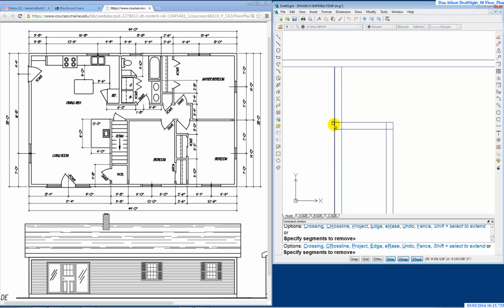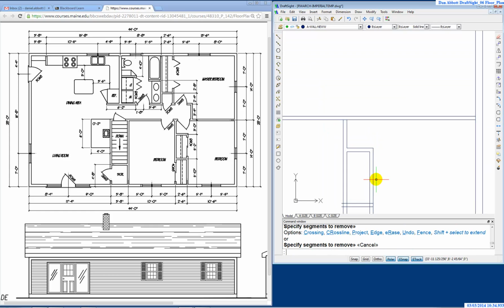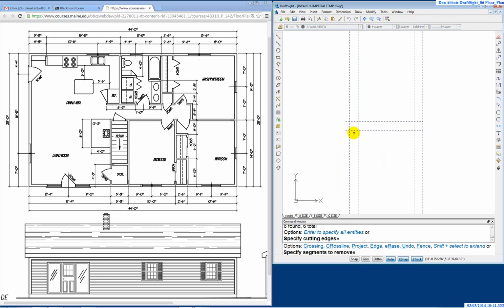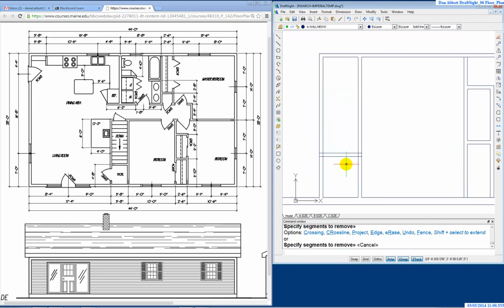Now I use a trim command, and I'll clean up this wall segment by picking each of these little pieces, including this one. And this one. Again, this is all with the trim command that I'm doing this now, after exploding the mlines, by the way. So I'll go back in the trim command. Those are my new trim lines. This is going to get trimmed back from here to here. Little section gets trimmed out there. That section gets trimmed out here, here, and here. So that's how you lay out the double line walls, and that's how you clean things up.